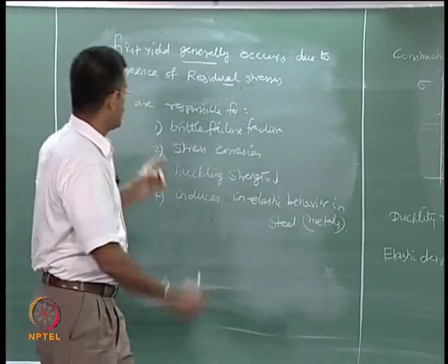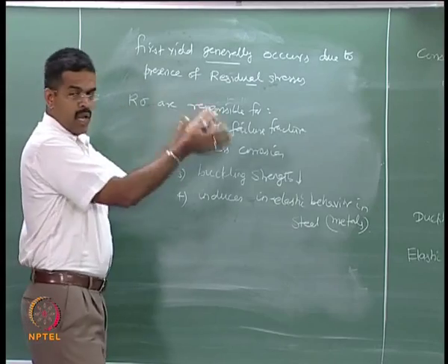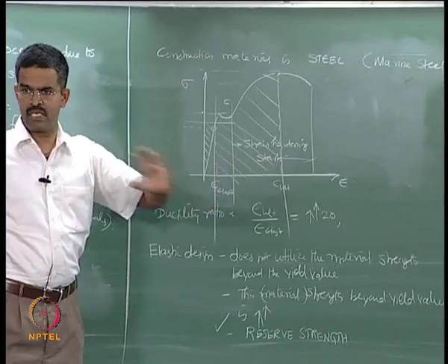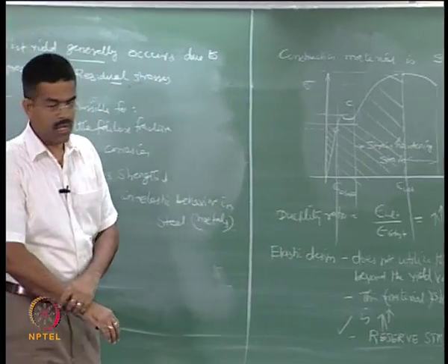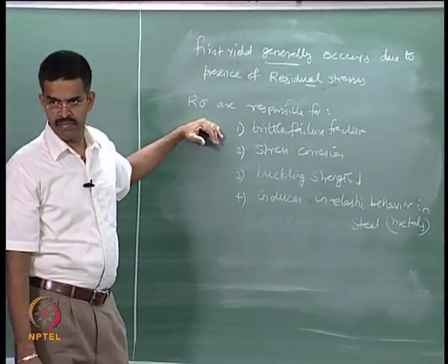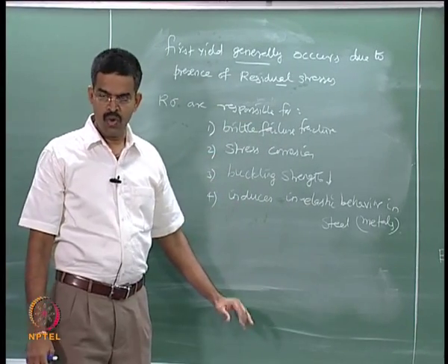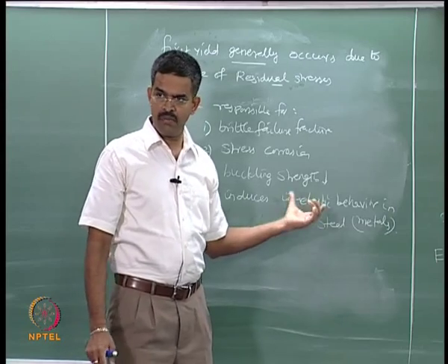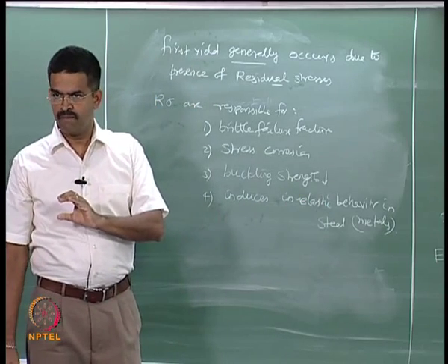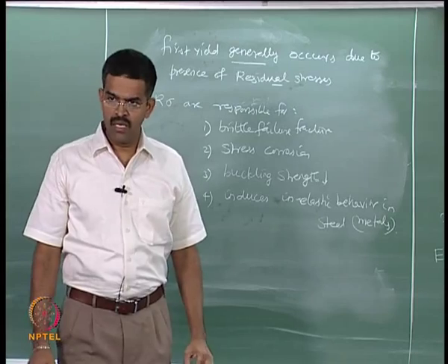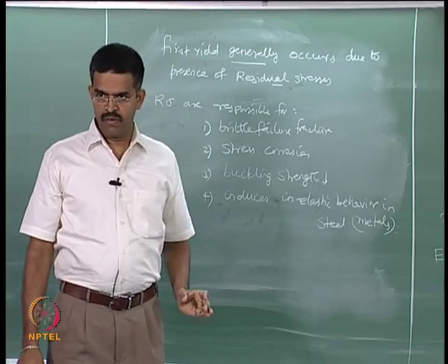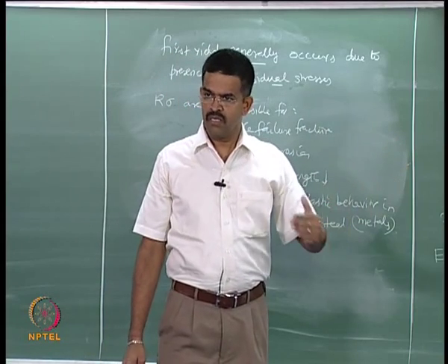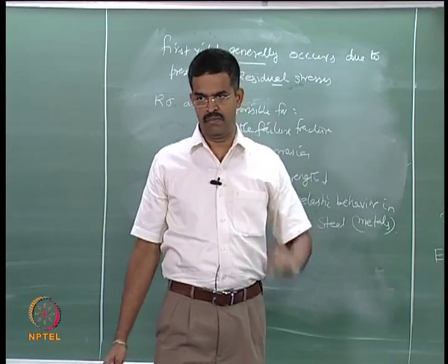So, the presence of residual stresses otherwise results in excessive deformation, which is a plastic or inelastic deformation. When the residual stresses cannot be avoided, can only be reduced, why not take advantage of that so-called inelastic behavior in my design? Okay, it is because of this reason that people have started shifting from elastic design to ultimate limit state design in steel structures for marine structural design.